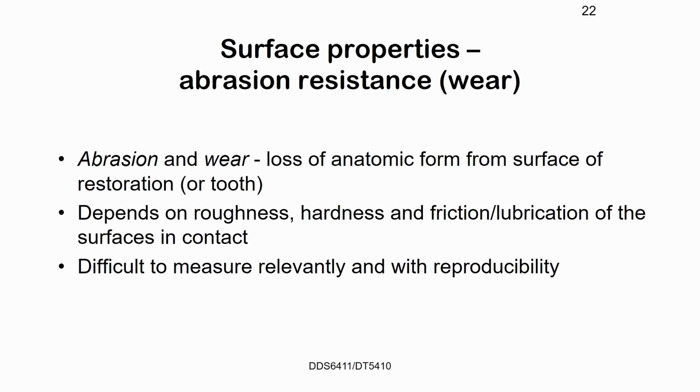So the measurement of hardness is related to wear resistance, or abrasion, scratching or volume loss from a surface. Again, it's a compound property. It depends on the roughness, obviously, or friction, and the hardness of the material we just mentioned.